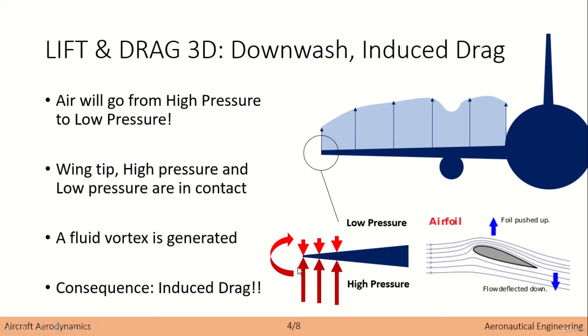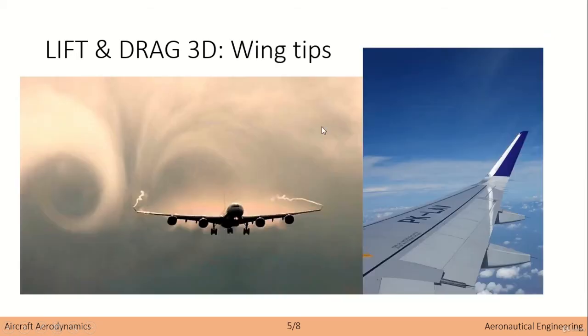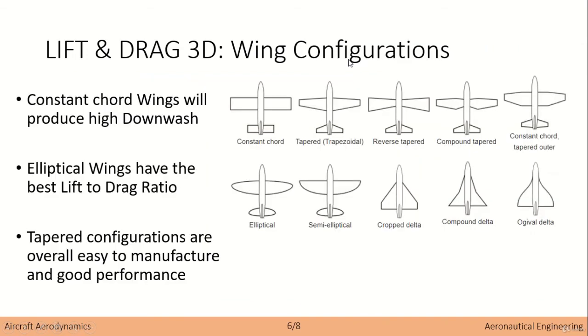Because if we didn't have any kind of wingtip, this curve would actually move to zero, because the lift is by definition just the difference of pressure. And if we don't have a way of separating the pressure on the bottom and on the top, we will come to lift equal to zero at this point. So what the wingtip allows is to actually improve the lift, okay, on the wingtip. This is the wingtip, okay, and this is why it is used very commonly in many kinds of different aircraft.